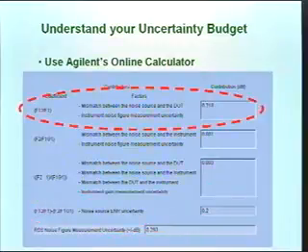The next big uncertainty is the input mismatch. Even with a reasonably good match, that's quite a large contribution to the uncertainty. Remember that this is root sum of squares, so those numbers don't add up to that.